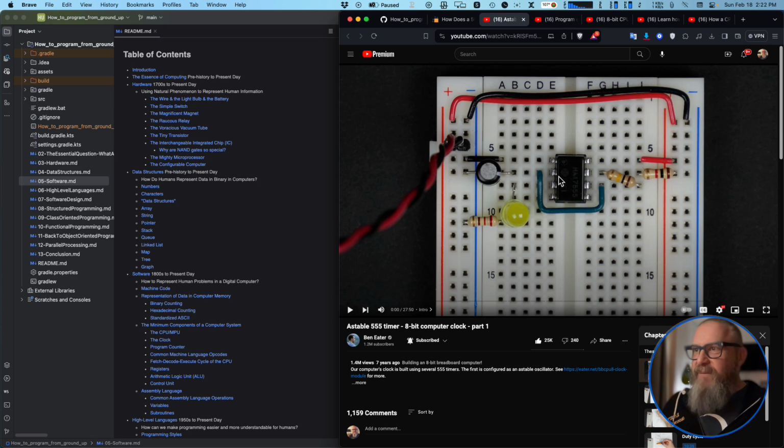There's the 555 chip, and it just says 555. You hook it up with resistors and a capacitor, and it does a certain frequency on and off, like dot dot dot or dot dot or dee dee. You can set any of the frequencies for how long it's on, how long it's off, all that stuff.